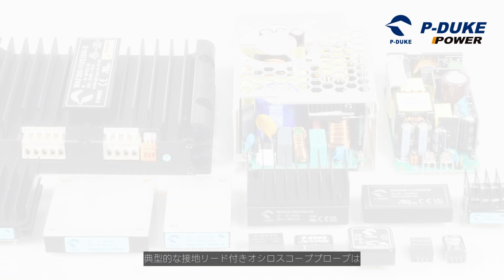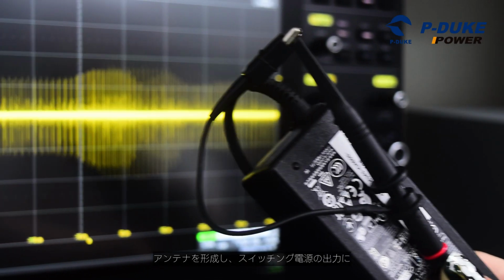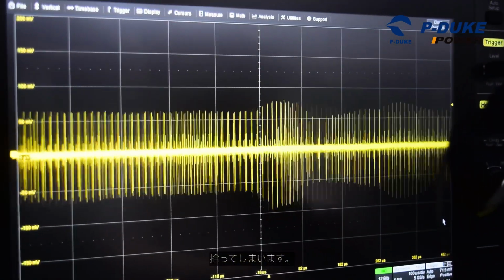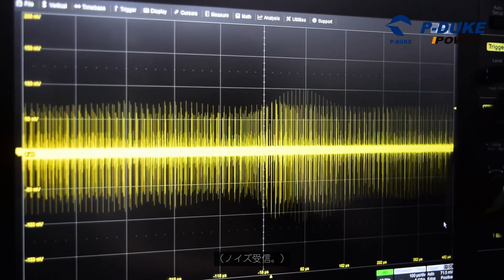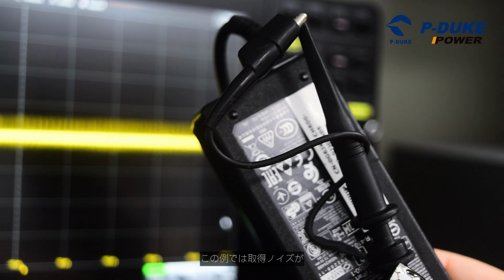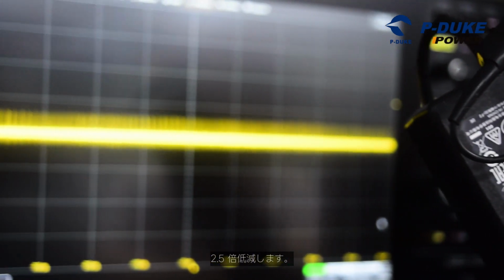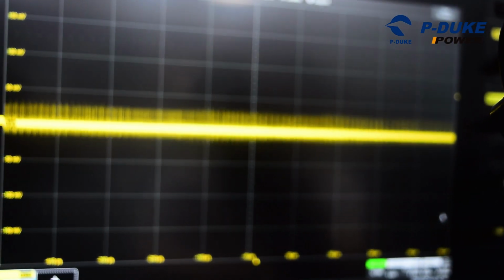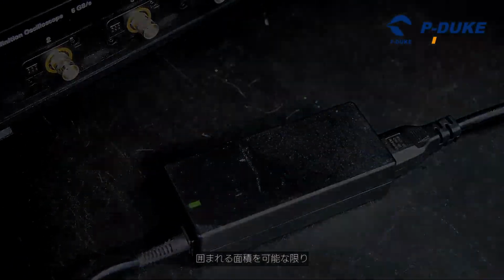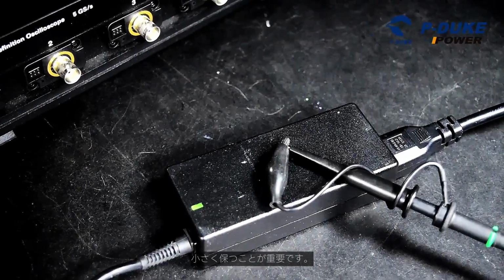A typical oscilloscope probe with ground wire forms an antenna that captures radiated interferences from a switched-mode power supply without even being connected to the output. If the ground wire is wrapped around the probe, the captured noise is reduced by a factor of 2.5 in this example. It is therefore important to avoid wire loops and to keep the enclosed area as small as possible.